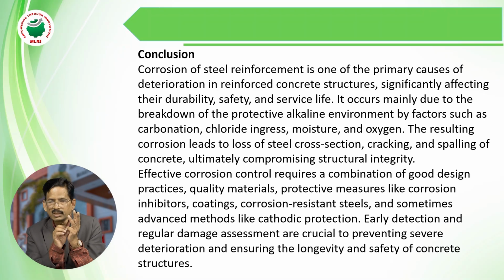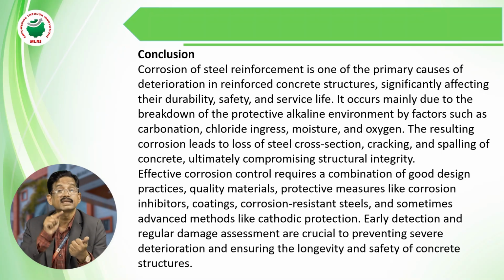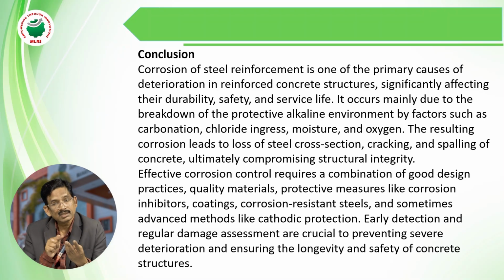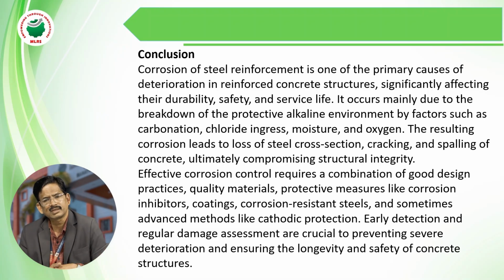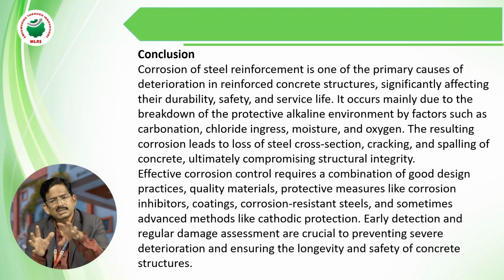Mechanical properties means compressive strength, flexural strength, split tensile strength and Young's modulus. These are only mechanical properties. Durability properties mean water absorption, how the concrete absorbs the water. There is the water absorption test, porosity test, rapid chloride permeability test, acid resistance test, carbonation test and void ratio test. These are different varieties of tests. Through these tests, we have to assess the durability of a particular structure.